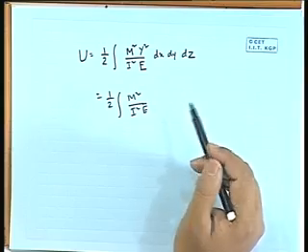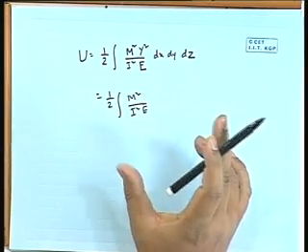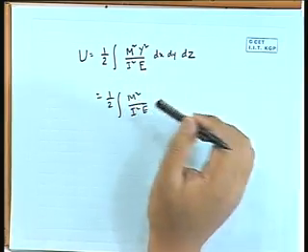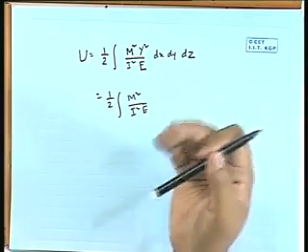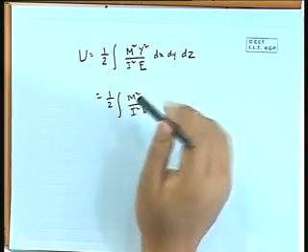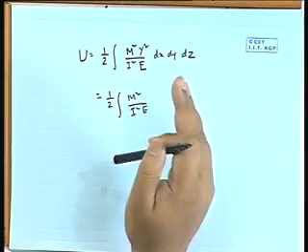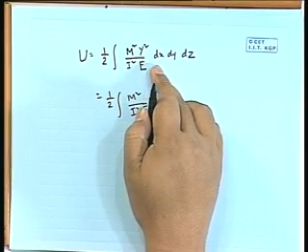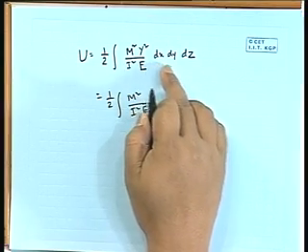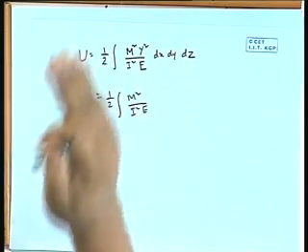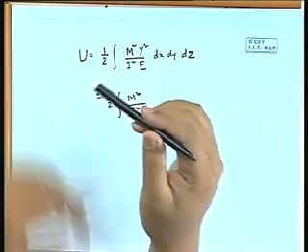Here you just observe I E, more or less this quantity will be a constant quantity. Here M will be fixed at a station, for a particular value of x it is constant. So, if we integrate about y and z, y z meaning along the cross section of the member, because this is x, it is y, it is z. So, along the cross section, at a particular station M will be constant. M will vary from one station to another station. So, here we can integrate.